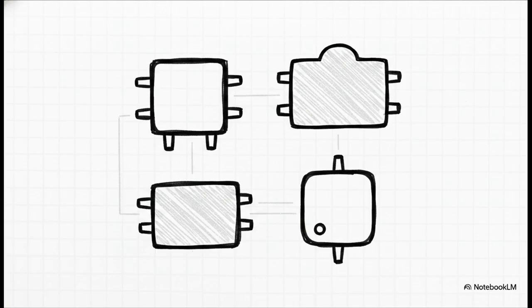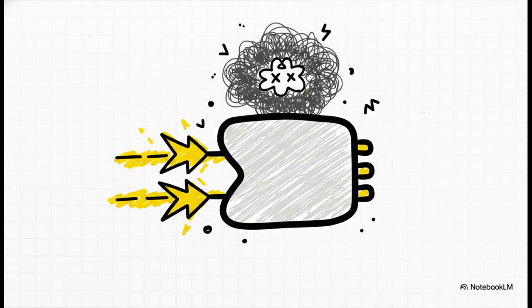We've got the SR, or set-reset flip-flop, the JK flip-flop, the D, which stands for data flip-flop, and the T, or toggle flip-flop. They each have their own totally unique behavior based on the input they receive and that all-important clock signal. Let's look at the simplest one first, the SR flip-flop. It has a set input and a reset input. You activate set, the output goes high. You activate reset, the output goes low. Super simple, right?